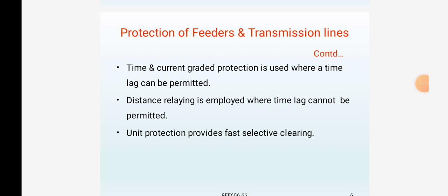With more generators and outgoing lines connected to the bus bars, it becomes necessary to sectionalize the layout so that a fault on one section does not cause a complete shutdown. This can be done by a circuit breaker, called a bus coupler, and isolating switches. The two bus bar sections are so tied up.